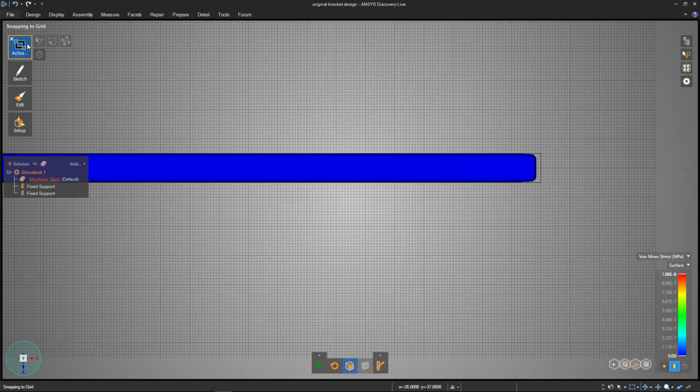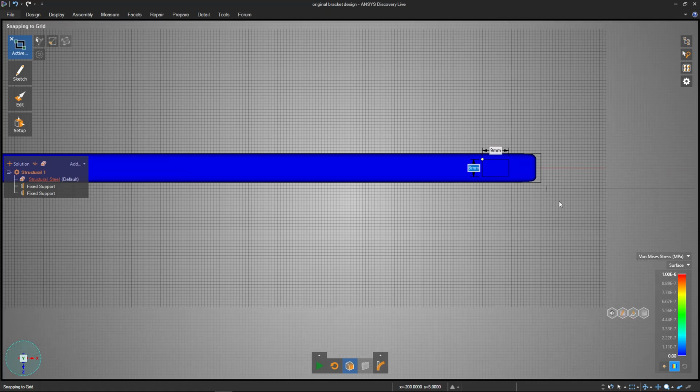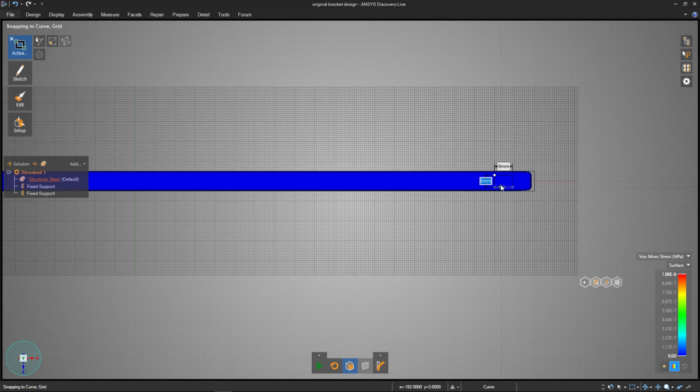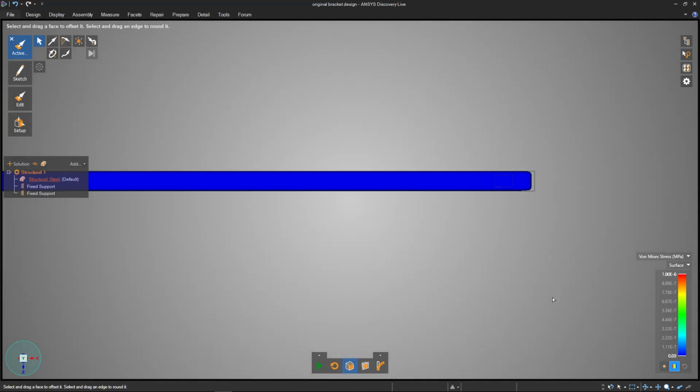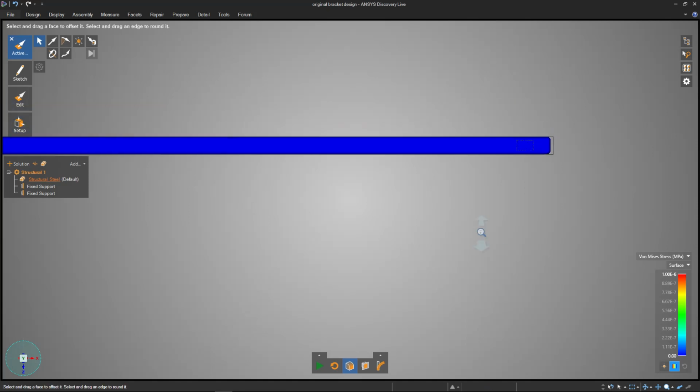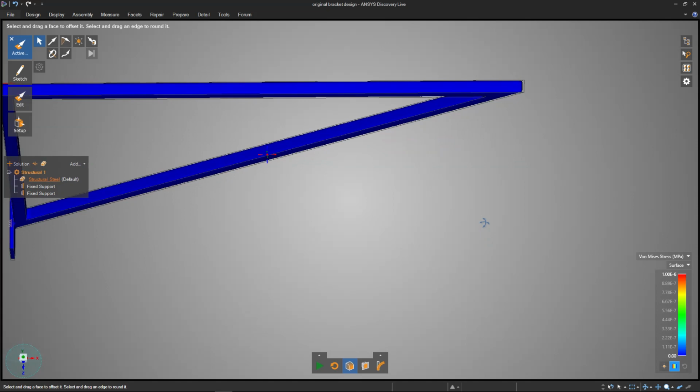So I'm already in the active tool, which is a rectangle. Let me just put a closed rectangle shape out here near the end. I'll hit enter once I release the mouse, just to make sure that that change has been committed. Great, now I've got this closed box. To go out of this sketching view, I have to click this little 3D model to end the sketch. That now means there's a new closed face right there at the end of the bar.